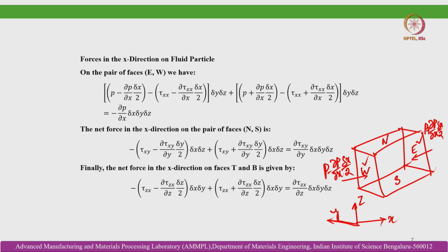Here one thing is there. Generally, for the notation of all other stresses like the shear stresses tau, the notation considered in this derivation is that the flux which is going towards the positive x coordinate is considered as positive, and that going towards negative x is considered as negative. The same treatment is applied for y and z direction as well. However, in case of pressure the treatment is a little different.